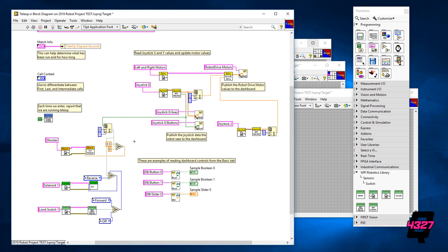So let's suppose you have a motor activated by a button, but you cap the power at 50%, and sometimes you'd like to go all 100. Here's how. You already have the true-false gate set up with if the button is pressed, the motor receives 50% power. What we now have to do is add another button with another true-false gate to multiply our power by a factor of 2. So go ahead and click and drag the button array to get another outlet for the buttons. Let's call the first button 0 and the second 1.